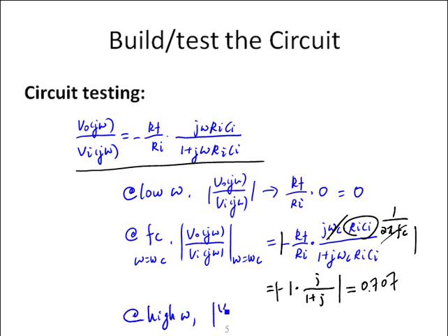When the frequency is higher than the cutoff frequency, the attenuation rapidly decreases to nothing, and the transfer function is getting closer to 1. That's why this circuit is called a high-pass filter. Next, I will show the input and output signals at a few different frequencies.